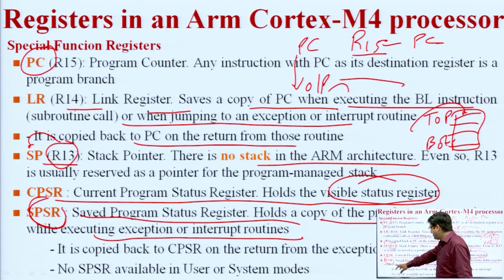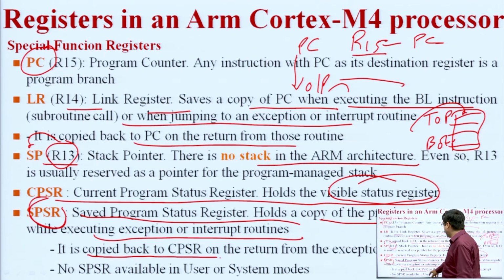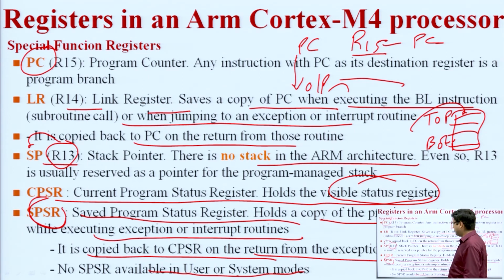So what is happening here? The SPSR is copied back, and after execution, all the values will be back in the CPSR. Okay, and no SPSR is available in user or system mode, so SPSR will not hold any value. After execution of the SPSR, values will further be provided into the CPSR.